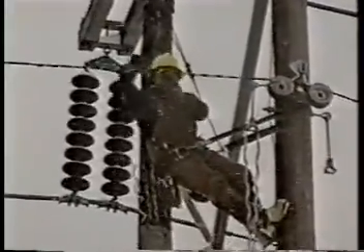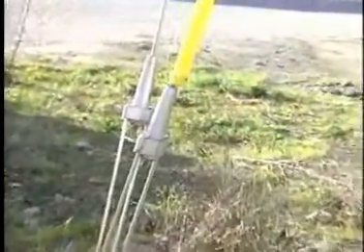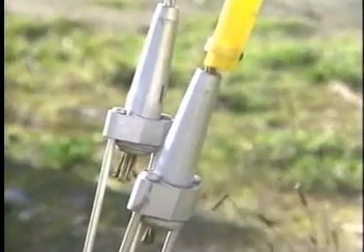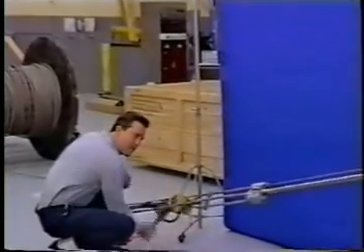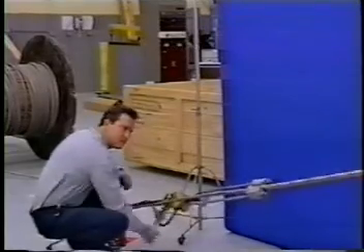At this point, the cable is not yet securely fastened to the pole to allow for tensioning. Installation continues until a number of spans have been installed. Usually, tensioning is done from a pole where head guys have been installed to provide firm support. Depending on the cable type and application, you may use block and tackle, chain hoists, or tensioning jacks to apply tension up to 20 spans at a time. Most specifications call for tensions ranging from 1,500 to 3,000 pounds. After the correct amount of tension has been applied, the cable is firmly clamped at pole locations.